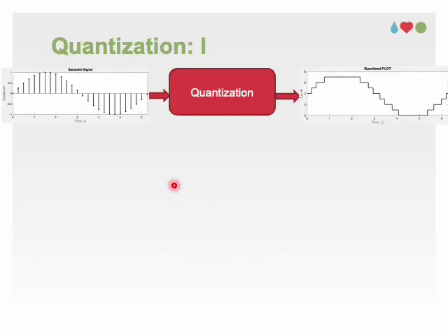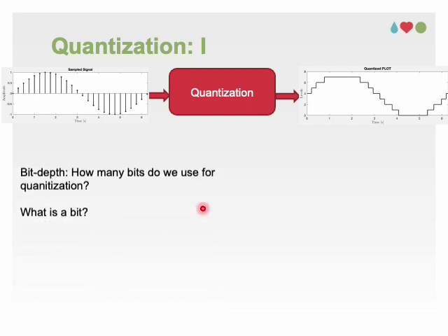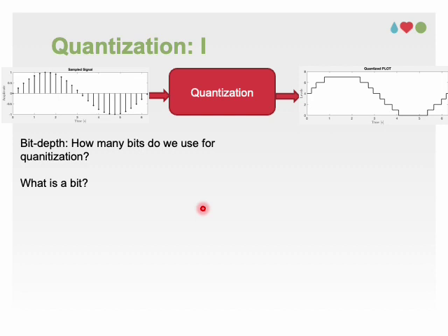Quantization is about discretizing the amplitude into a number of levels in the vertical axis. For this, we need to define, like the sampling interval, the quantization levels for the vertical axis. Here we define the resolution in the vertical axis in terms of bits, say 3-bit, 4-bit, 8-bit. We then say our ADC has, for example, a 3-bit code.